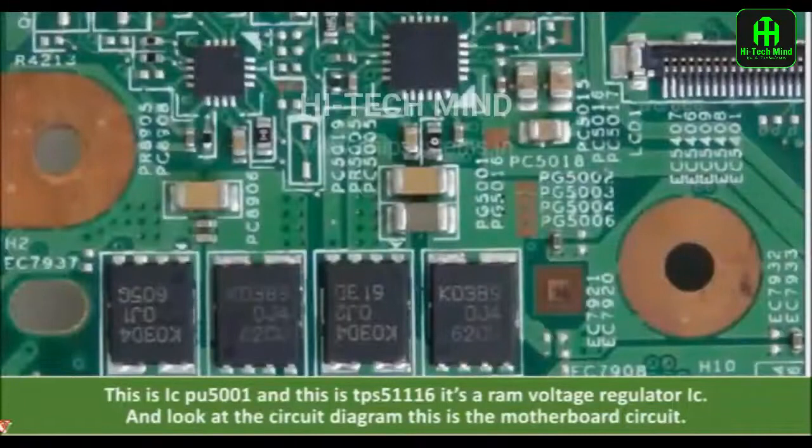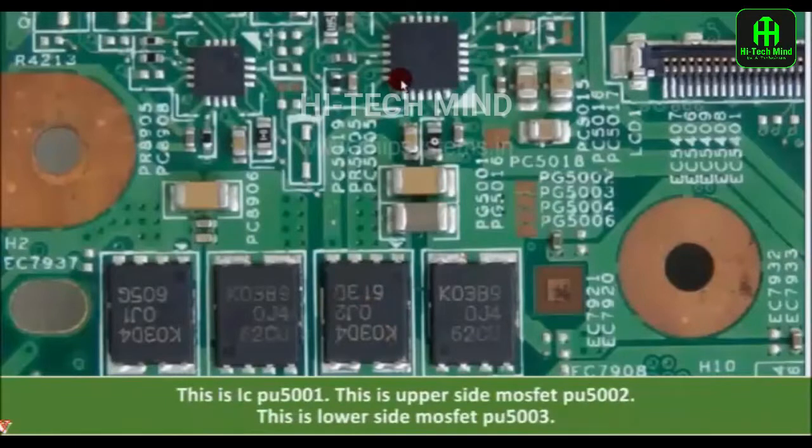And look at the circuit diagram. This is the motherboard circuit and this is IC PU 5001. And here we are seeing the upper side MOSFET PU 5002 and this is the lower side MOSFET PU 5003.